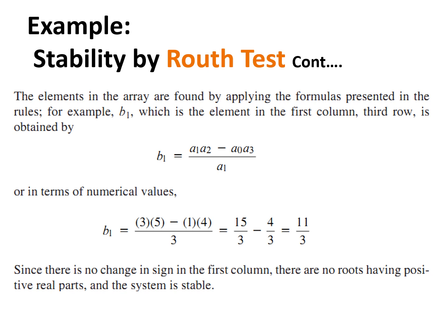So this is the Routh method of checking stability of a system. You can just use this, or if you have the roots of the equation, fine. If finding the roots of the equation is tedious, you can use this Routh method to find whether it's stable or not, how many roots are on the right half plane or on the left half plane, and then see whether the system is stable or not. So stability is important. It's not just getting the set point or disturbance change; to get set point and disturbance response, you have to make sure first that the system is stable.